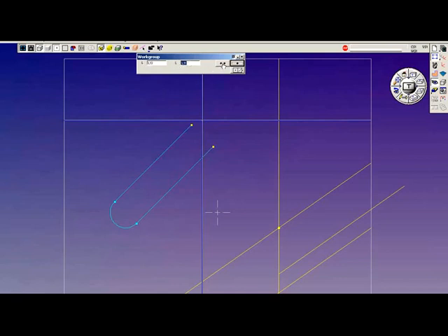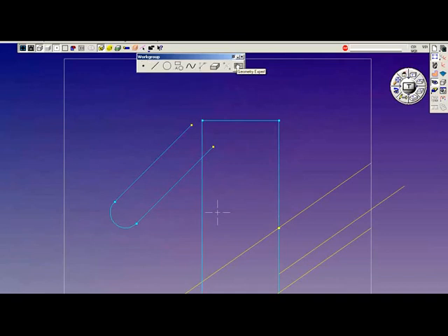I select the multi-feature creation tile to keep the window open. It generates a point, and then I can just go down the line, connecting intersection after intersection without the need of the shift window or the control key. So you activate it one time, and then you just select features and connect them. This is handy when you have a large number of features that you want to connect. When doing 1, 2, or 3 features, you may revert back to the shift, drag, right mouse click, connect method.